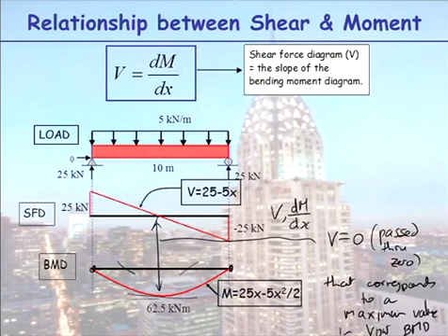So once you draw your shear force diagram, which you can easily do, you have a go at drawing your bending moment diagram. And then you say to yourself, okay, what are the rules? This shear force is positive, it has to slope downwards. The shear force in here is negative, it has to slope up. The actual slope is big, it's getting smaller and smaller and smaller.